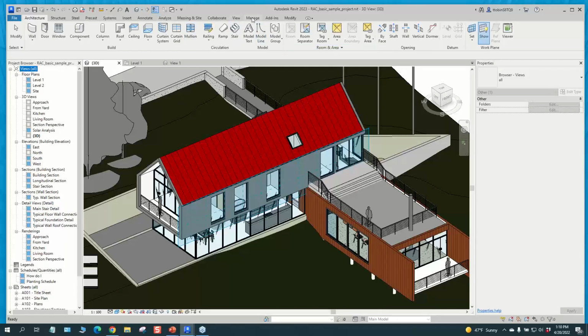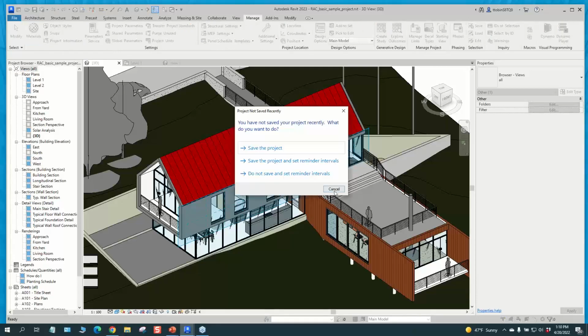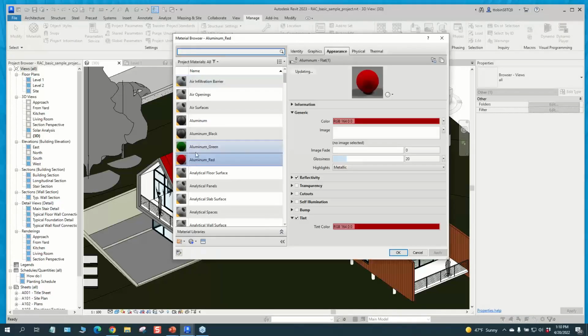The other one that I was talking about was up here in materials. So if we come into the materials, now all I have to do is right click and say duplicate the material and the assets. Before, if I duplicated it, I would have to make sure I came up here and told it to duplicate the assets. Now I don't have to do that.